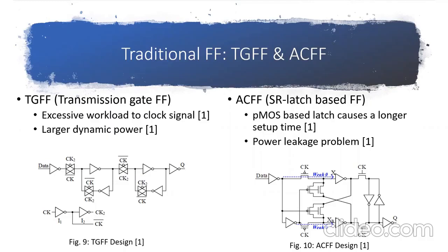Another type, SR latch-based one, also has some downside. Since it is a PMOS-based latch, it causes a longer setup time. Also, it has some power leakage problem when certain input and internal node combinations occur.